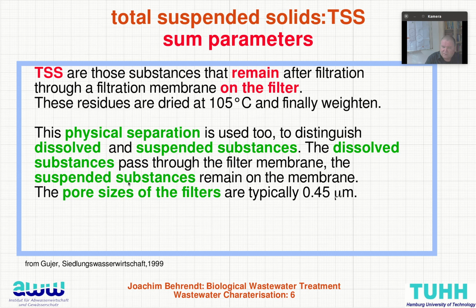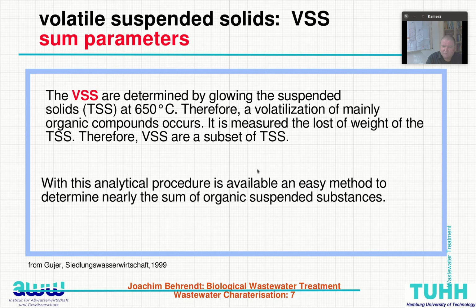This separation method is also used to distinguish between dissolved and suspended substances. The dissolved substances pass through the membrane filter, and suspended substances remain on the membrane. Typically we choose 0.45 micrometers for the analytical method. For special topics, other filters are important as well.